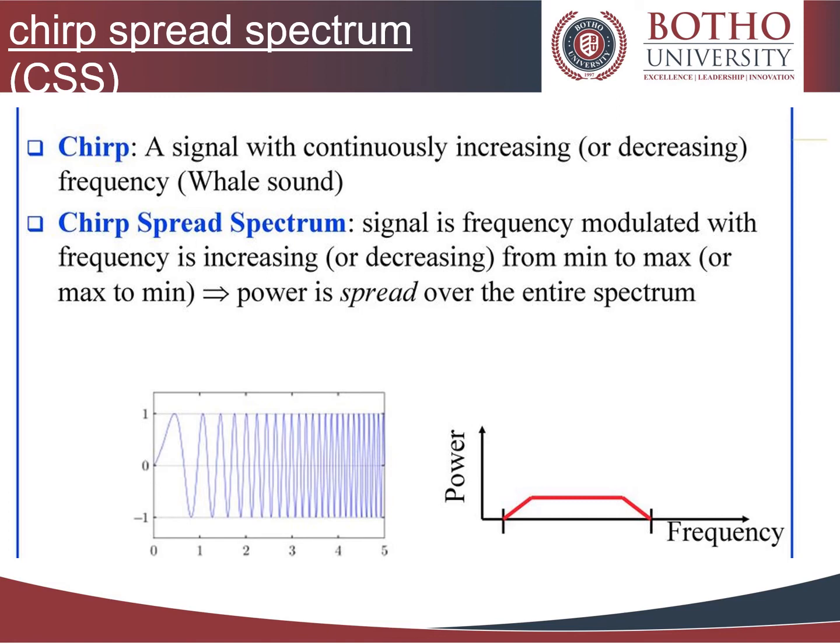However, it is unlike DSS or the frequency hopping spread spectrum in that it does not add any pseudo-random elements to the signal to help differentiate it from noise on the channel, instead relying on the linear nature of the pulse. Additionally, the CSS is resistant to the Doppler effect, which is typical in mobile radio applications.